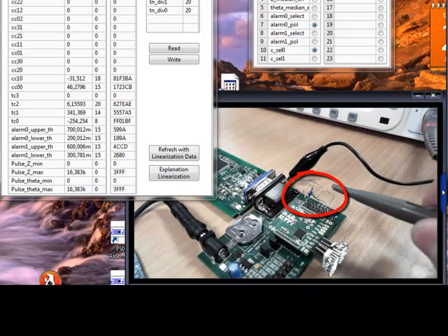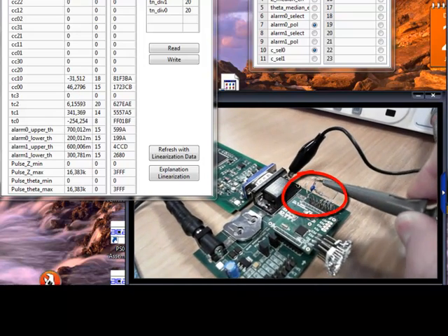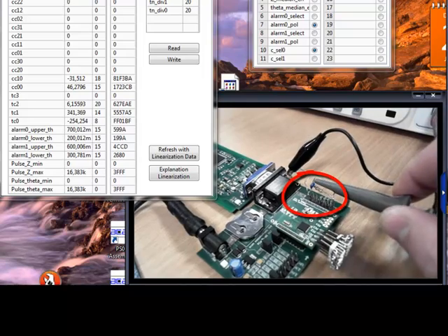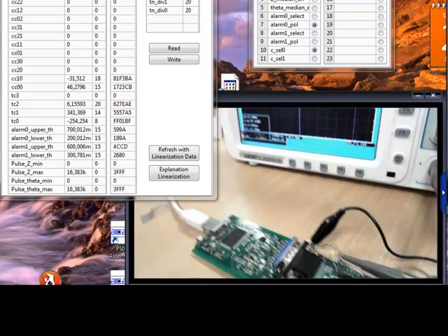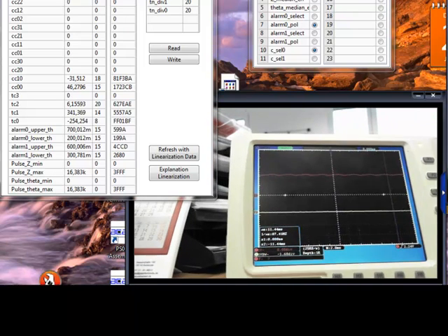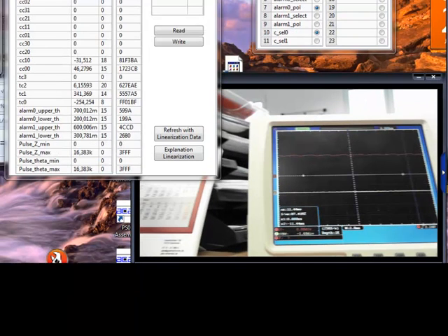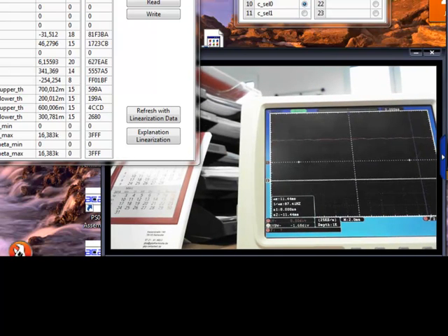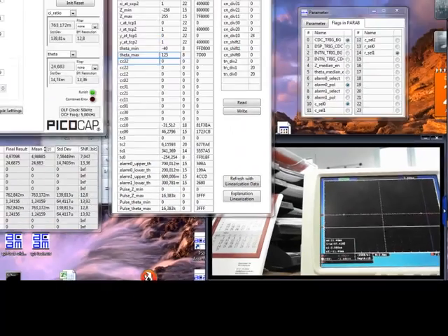I have here a simple first order low pass filter, as you can see here, and I connect the probe of an oscilloscope now to it to show you the analog voltage output. Now we have the corresponding analog voltage for the 70 to 30 duty cycle, and if I change the capacitance, since we get the high and the low voltage signals accordingly.